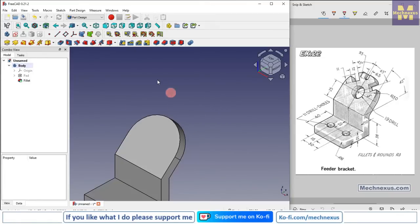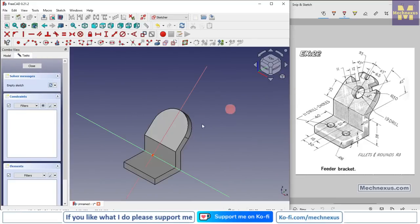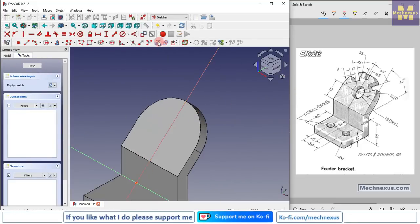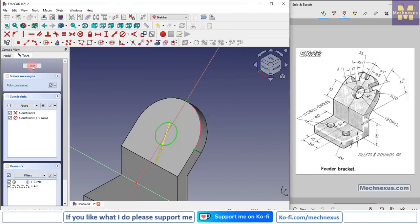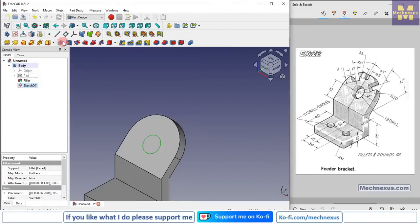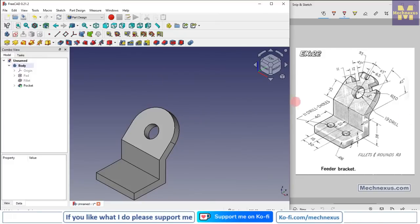and press 0 and select the sketch, and we will project this diameter and select the circle, and here is a 19 mm drill. Select diameter, provide it 19 mm, click on close, select the sketch, click on extrude cut, and from here set it through all, say OK.